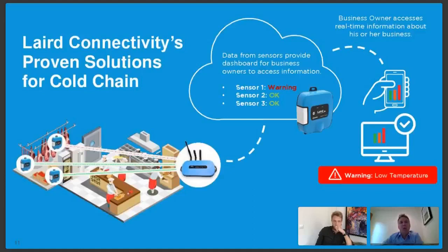So we were using Bluetooth Low Energy to talk to remote Bluetooth sensors, and then LoRa for the long range bridge to a gateway for the longer range connection to an IP-based cloud network. And then what we found is the BLE inside of these devices could be used to have a local wireless display. You could use a smartphone or a tablet as a way to have a look at the data or to do configuration or control of the LoRa device itself.